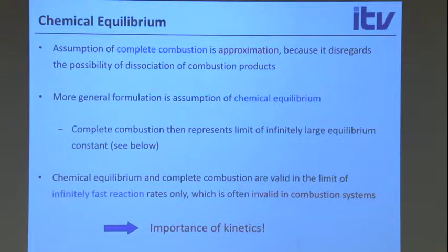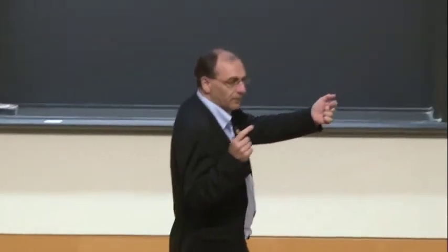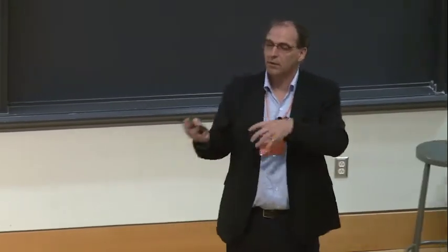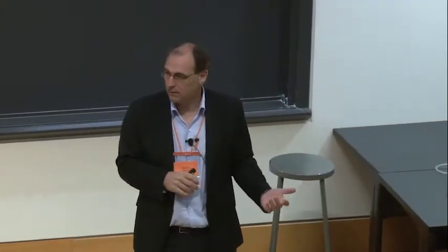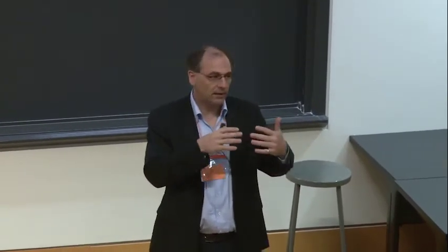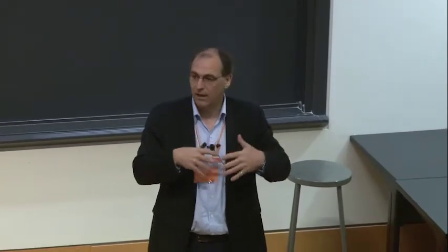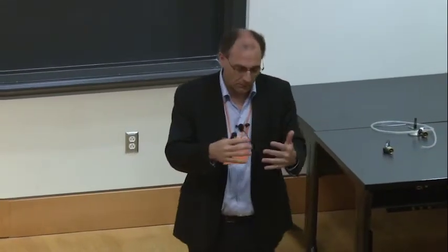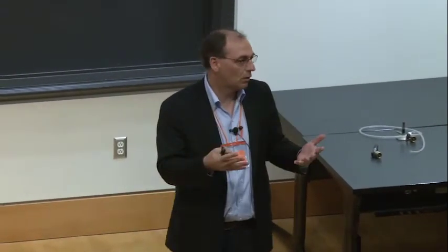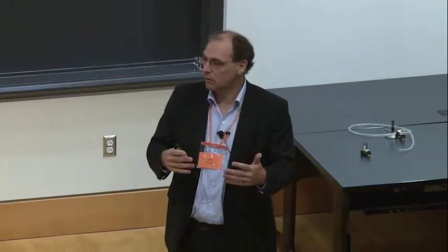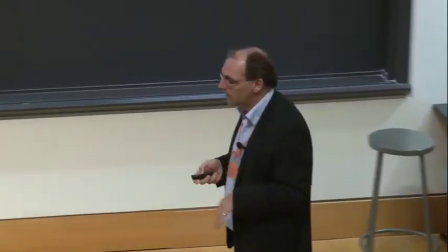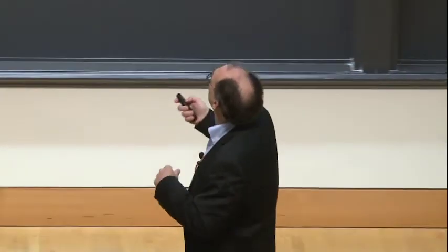But in reality, this would never happen. You always have reactions going both ways. They go forward and reverse, and you will never convert all fuel and oxidizer to products. You end up somewhere in between. Where you end up, that depends. After infinitely long time, you reach chemical equilibrium, and that is somewhere in between. And where that is depends on the local conditions. And how that equilibrium composition depends on the local conditions, we can see from the second law of thermodynamics.